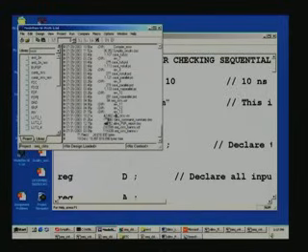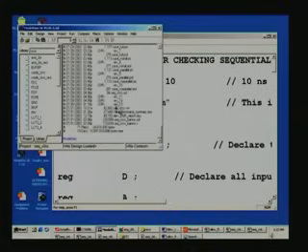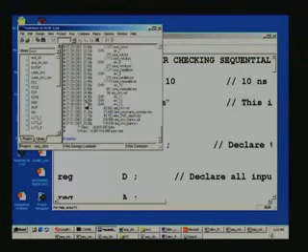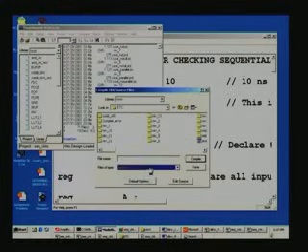It is a huge file, some 42,000 and odd, and so now what we need to do is compile this once again. In this test bench we have replaced it with the .vm file, so it will take this as a design file now and then compile. So, let us see what it says. In the compile window, we need all files at the bottom, then only you can view this.